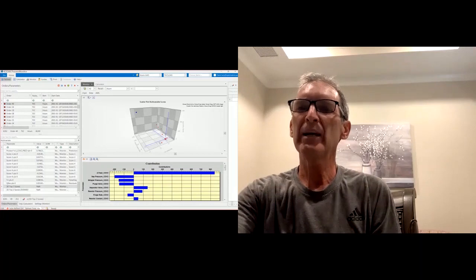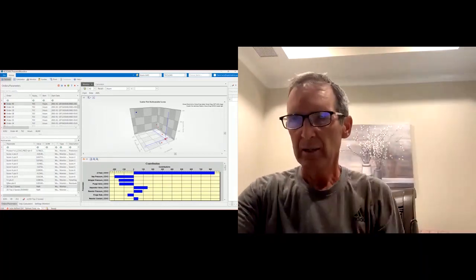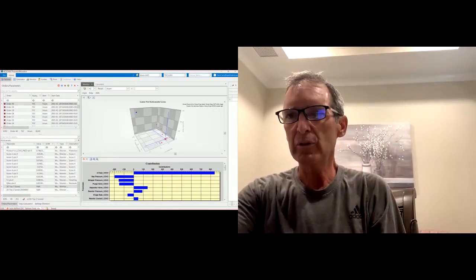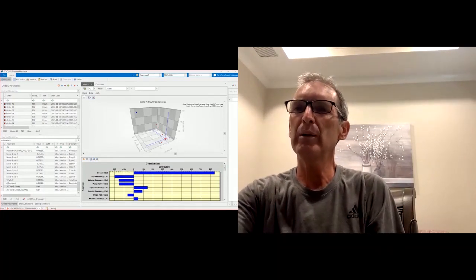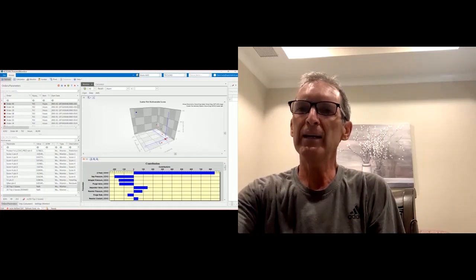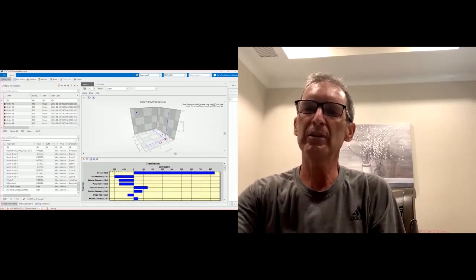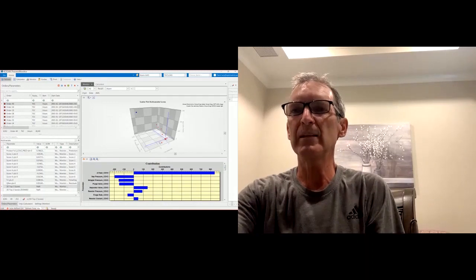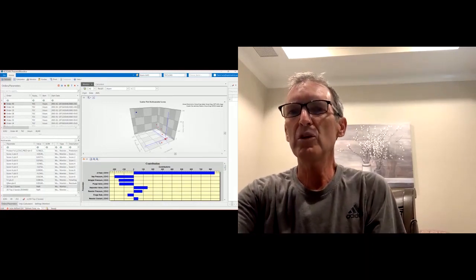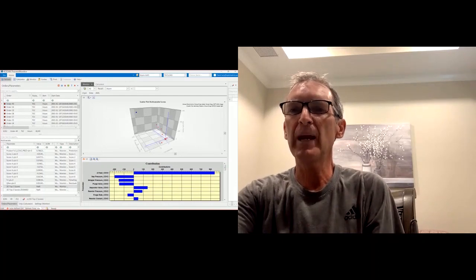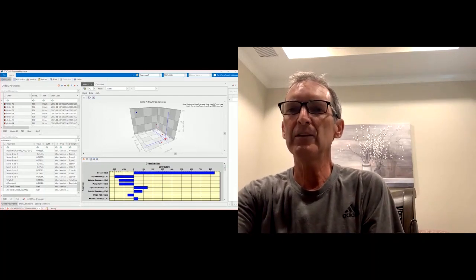And then it takes you back to the univariate chart, which shows you, in the upper right quadrant, the one parameter that's in left field. And that's the one that's created by the chart down below. It's a temperature trace of the parameter of this A feed. What this shows is that about a third of the way through the batch, the A feed just stopped.